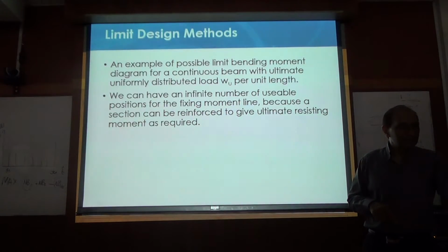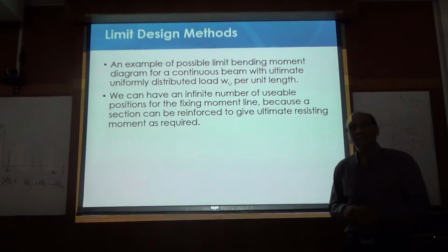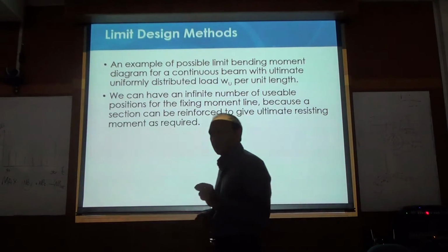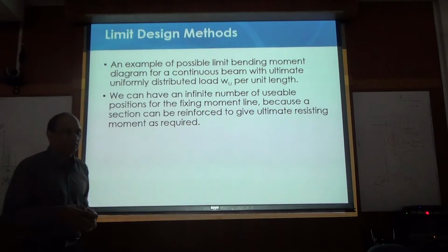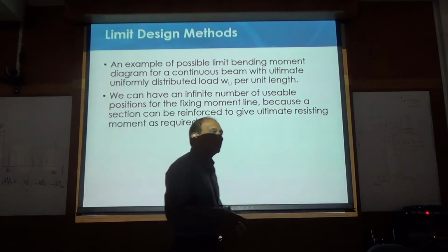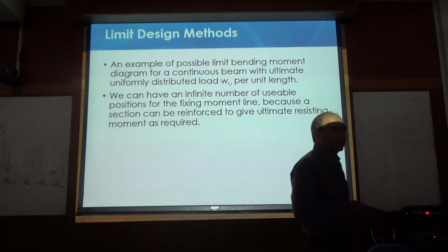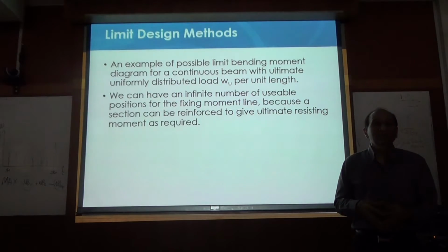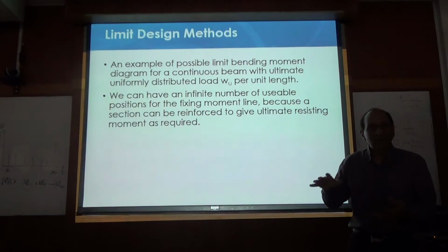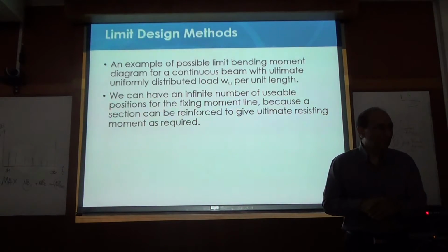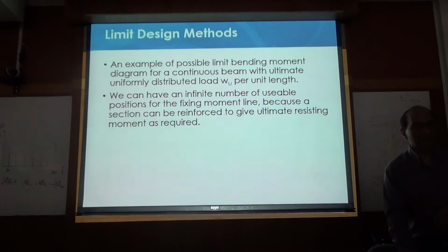Yes, good. One more. Temperature. Temperature and shrinkage are the two most common causes of cracking, which most of us do not study well. We do not understand well. But those are the ones that we miss, and those are the ones that cause cracking. They combine with the other stresses and cause cracking. And all of the code equations for minimum reinforcement do not really work well. Anyway, that's another topic we will discuss some other time.